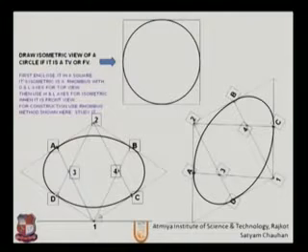So from 1, draw the biggest radius first, distance equal to 1 to A, and then repeat the steps from 2, the distance will be the same, from 2, C to D. The remaining 2 arcs will be smaller arcs, with radius equal to 3 to A, keeping the point on 3, and the same arc from point 4, B to C, and this will be the same in this view.